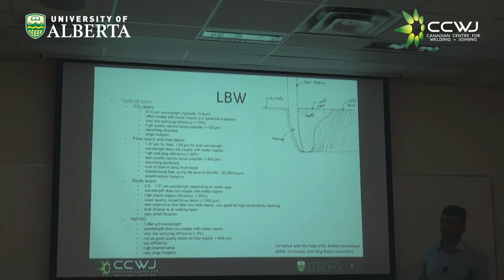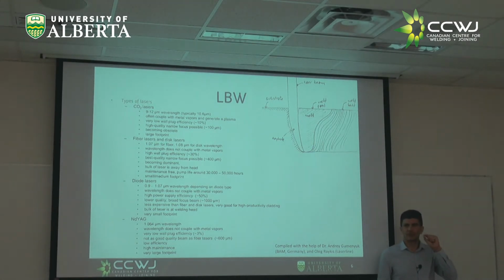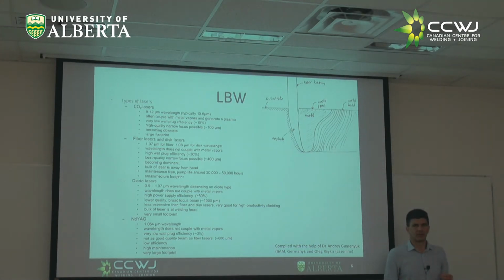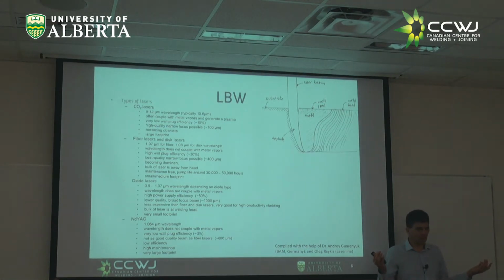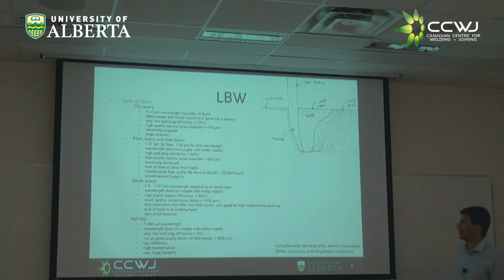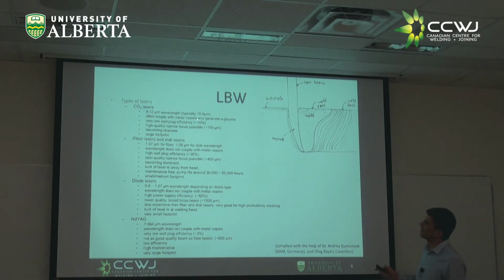CO2 lasers can give you an even narrower beam, because of the physics that generate the light. CO2 lasers can give you a 100 micron beam. Now, you can ask, how about a 1 micron beam? Well, eventually it gets to a point in which it's a knife. You're just cutting. You cannot possibly weld. So this difference in the spot size is important.